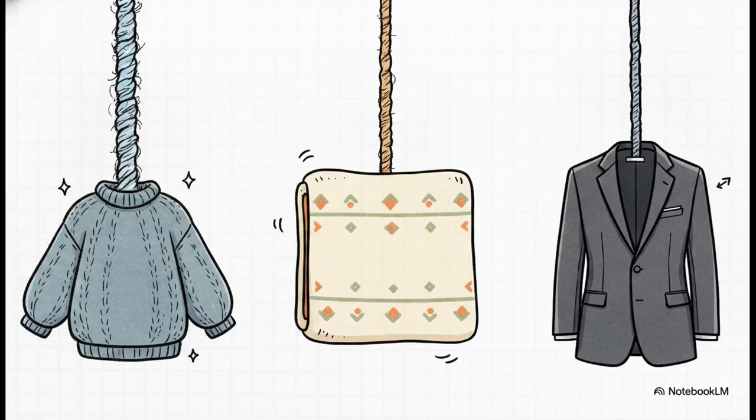When we look at long staple yarns, we get this really fascinating contrast across three main types, which you'll see in the bullets here. First, woolen yarns. These completely skip the combing step to stay bulky, hairy, and soft, which is exactly what you want for a cozy sweater. Second, worsted yarns. These are fully combed and parallelized, so they're smooth, crispy, and incredibly durable, the absolute ideal material for a sharp, lightweight suit. And third, sitting squarely in the middle, is semi-worsted, which skips the extreme combing, making it totally perfect for something like a blanket.